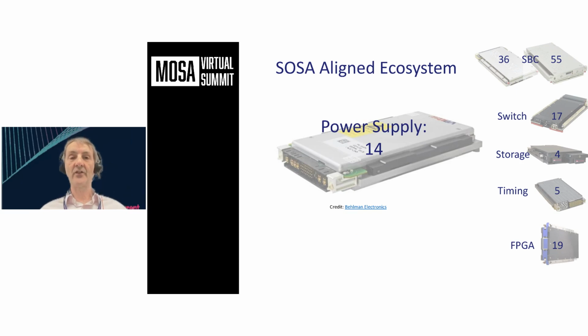So the great thing about some of the work that SOSA has done is that in the original VPX specifications, you could power your payload cards from either +5 or +12 volts. So when an integrator came to construct their system, they would very often have to specify a custom power supply that had X amount of watts on the 5-volt rail and X amount on the 12-volt rail. That's now gone away. So everything is +12 volts with a +3.3 volt aux power, which is used for the management interface that runs in the background, either out of band or inband. And these power supplies now are effectively available off the shelf to suit the number of payloads and the wattage you've got in your system.